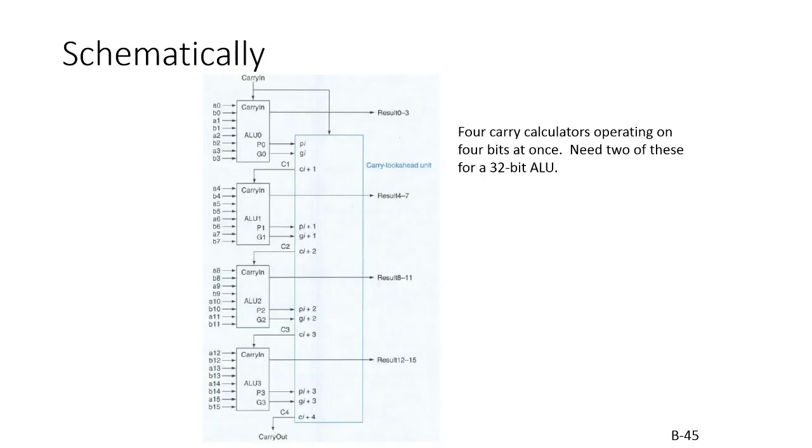That's pretty cool, because what we can do now is basically instantaneously accomplish the addition, which is fundamental to all the operations that we do in the ALU. As I showed you in the picture earlier, set less than is based on the addition, branch equals is based on the subtraction, and then we can do multiplication through shifting and other things. So this is a pretty big speed up in the common case, right?